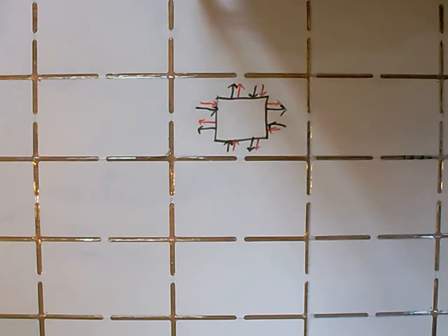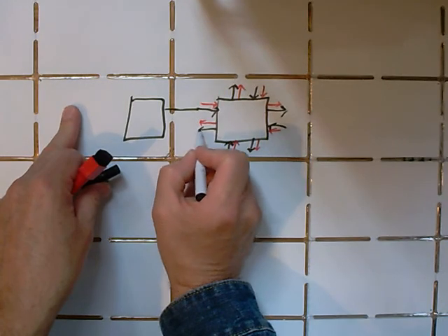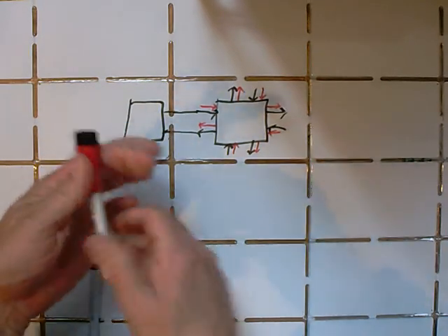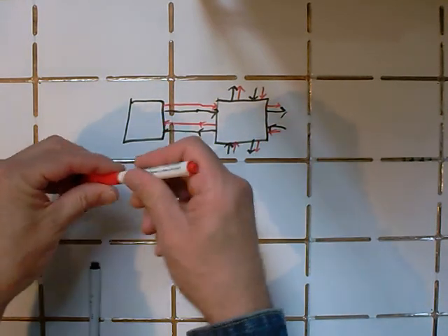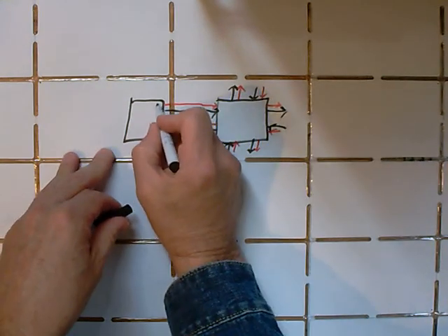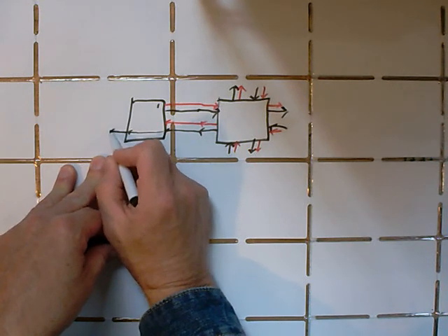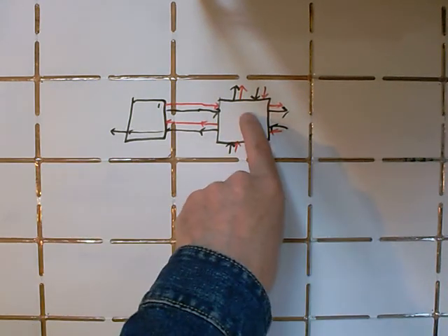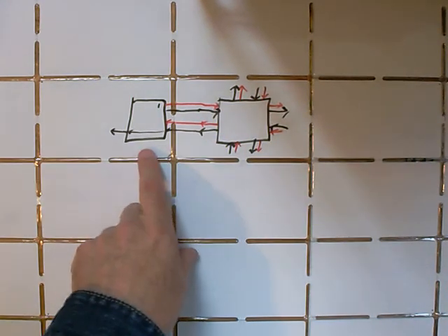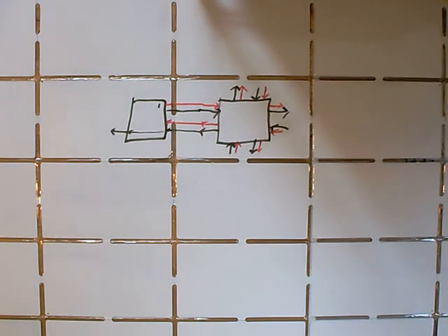Let's take a look at a 2-cell circuit, and all of these connections are set up in the way you would expect, but I'm going to just draw a few of them. And I'm going to set this cell up to put a 1 into the C input of its neighbor, and take the D line that's coming out and pass that over to the western edge of this cell. And now this cell here is reading the contents of this cell's truth table and sending a copy of that bit stream from its truth table out to its western side, where some other cell can be taking that bit stream and doing some processing with it.